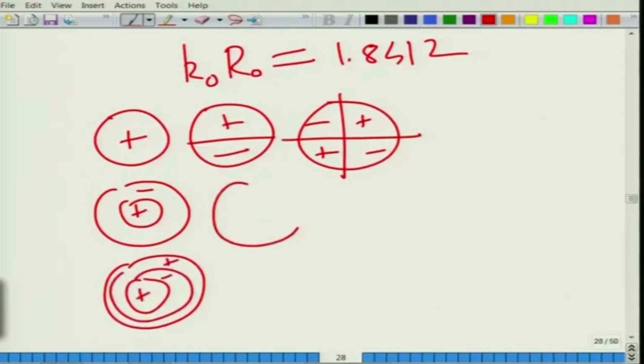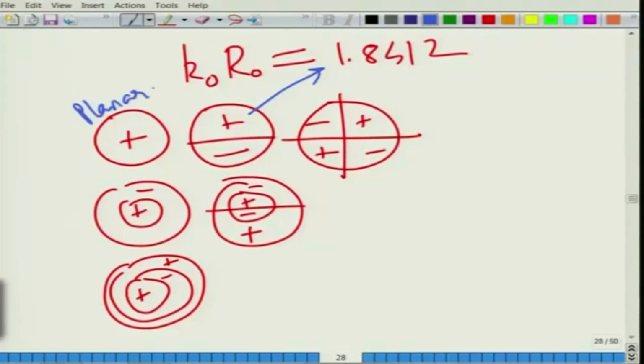There will also be cross modes. We are talking here about the cut on frequency of the lowest first higher order mode to propagate. The planar wave mode always propagates for a rigid duct. This is the cut on frequency of the first higher order mode, also known as the 1-0 mode. Recall the lectures from week 2.